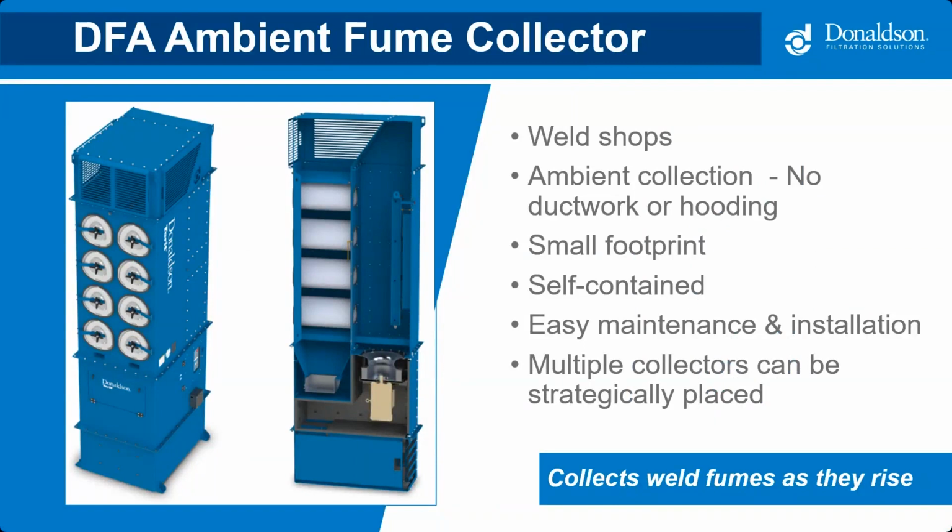It is a tall tower type collector, which means it doesn't take up much floor space. The fan is integrated, so it is completely self-contained. It's also really easy in terms of maintenance and installation, and it uses the same type of cartridge filters as the DFE. For large facilities, multiple collectors are strategically placed throughout the facility to create a racetrack effect of air movement.